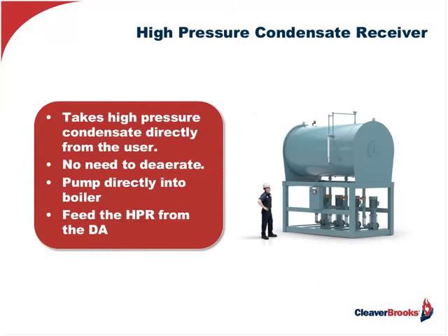So these high-pressure condensate return systems have been properly sized, properly controlled, and have all the devices on them, level devices, flow control devices, and pumps, to be able to withstand those high-pressure returns. Now what we've done is not only saved those BTUs, because now we're talking maybe close to 300-degree water in this tank, let's say we're at 80 or 90 pounds. We've also saved the chemicals, and we're saving that water. So significant savings as a result of a high-pressure condensate return tank.